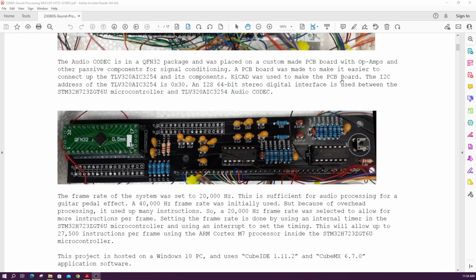So this is another free software package you could get that will allow you to make printed circuit boards, and it makes these Gerber plot files, and then you send it out, and then the boards come back, and you have to mount on the components yourself. You have to solder them on yourself. I suppose you can get them already made, but it's probably pretty expensive. But it costs maybe about say another $30 to get 3 of these boards made. So the TLV320 AIC 3254, maybe that chip costs about $5. So this whole thing, all the parts might be about $40 or so.